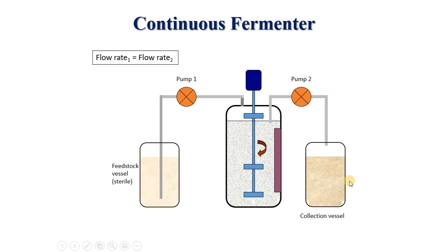So you can maintain the level of the fermentation vessel in a constant manner. That means you have to maintain the feedstock vessel, that is the sterile feedstock vessel, and the collection vessel. Both should be in sterile condition and a closed environment, without any possible contamination.